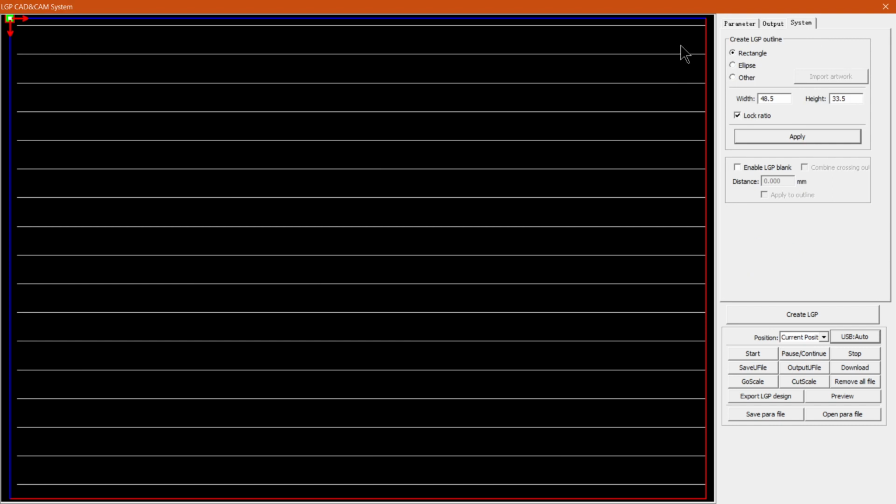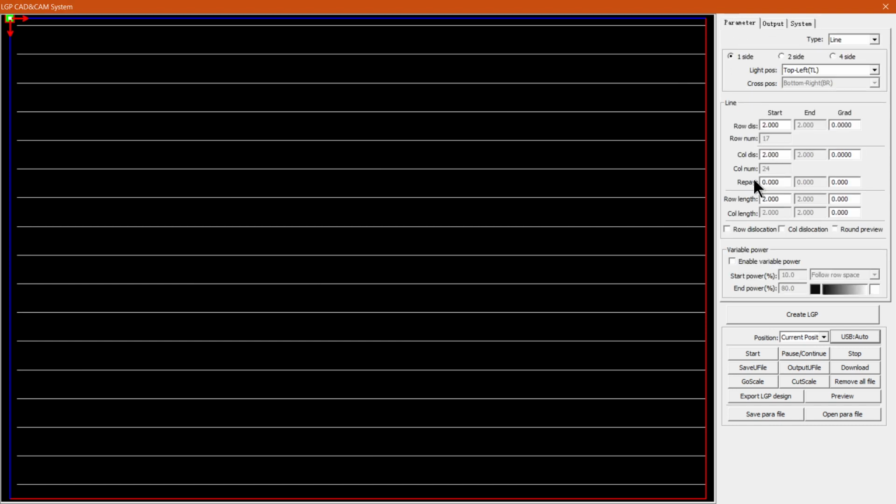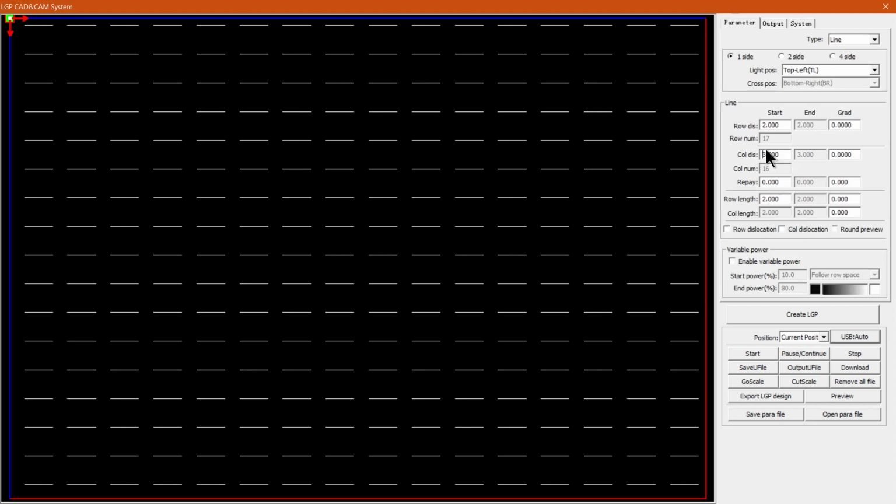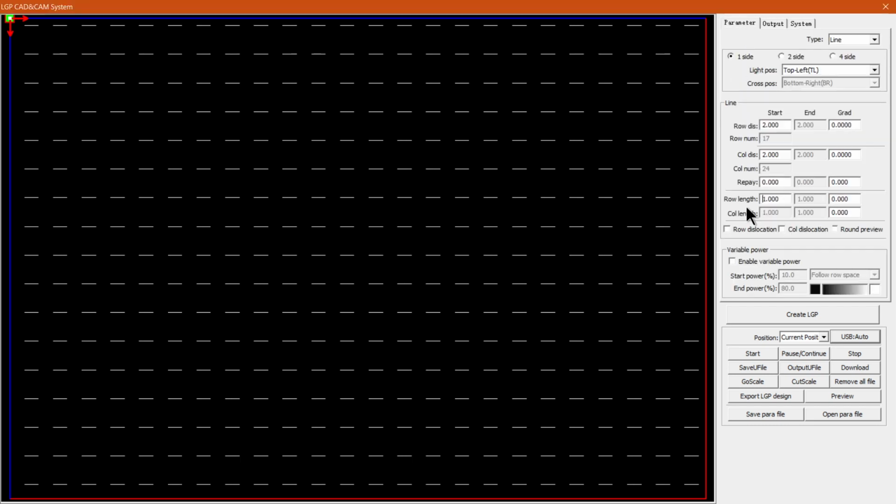Now what's happening is our spacing and our line width now exactly line up, so it makes a solid line. So if you had to change your column spacing, then we would start seeing a space there. If I took this to 3 and click apply, you will see there's actually still space. So that is something to keep in mind when you're setting the width of your lines, that the spacing works relevant to the actual length of them.